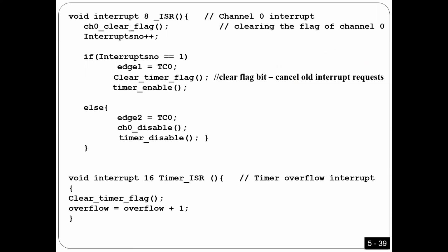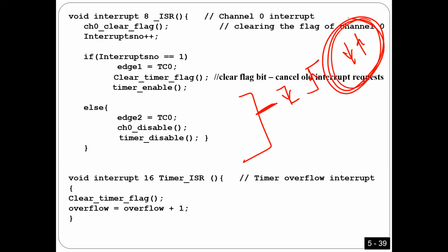I want to tell you something also. I know it's somehow tricky for students. Listen to me. It happened to me before, and I'm going to tell you what the issue is. Now, to configure the pin, as I told you before, I can capture only falling edges. I can capture only rising edges. I can capture both falling and rising. Is that okay? So in this program, it seems to me I already selected this one. I want to capture both, right?